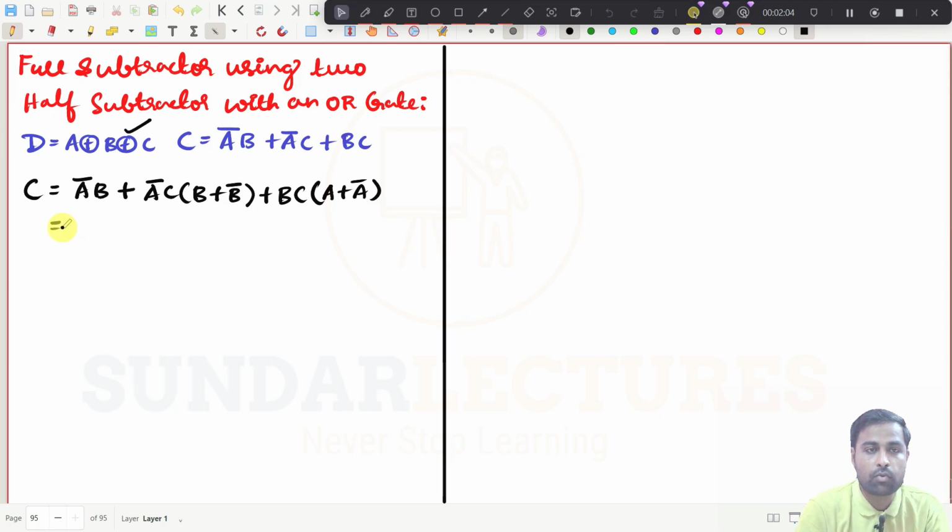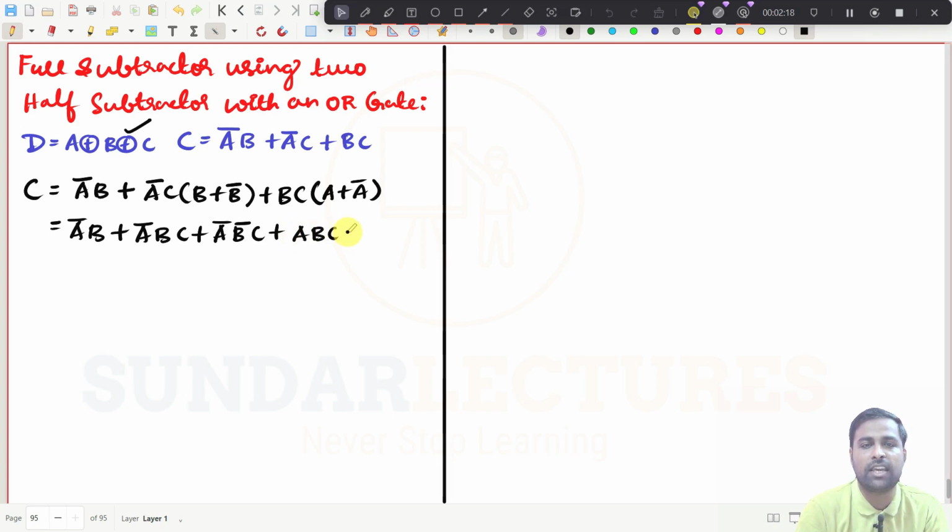Simply. And now what you do, you take this A bar B as it is now, and this will be now A bar BC, and then plus A bar B bar C, and then here also it will be ABC plus this will be A bar BC. And you can see these two are the same term, this one and this one. So what you can do now, you can neglect this one, and you can now write the common term in these two. It is A bar B. You take it commonly outside, it will be 1 plus C, and you can see here what is the common term in these two. It is C, right?